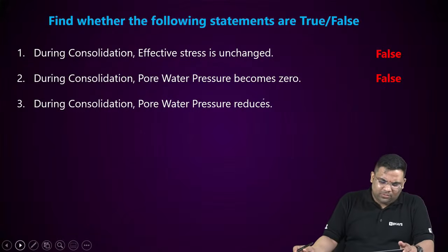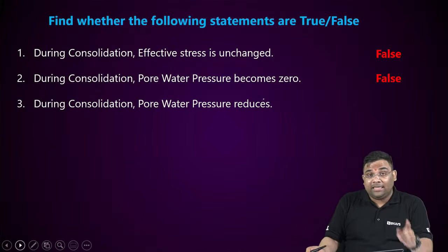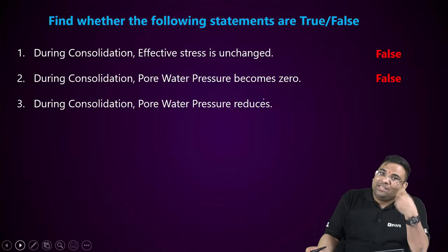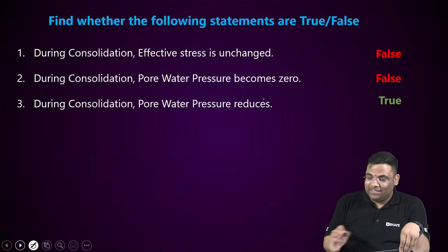Yes, this is true. During consolidation, pore water pressure reduces. Yes, it just doesn't become zero. But excess pore water pressure reduces and becomes zero. So this statement is true.